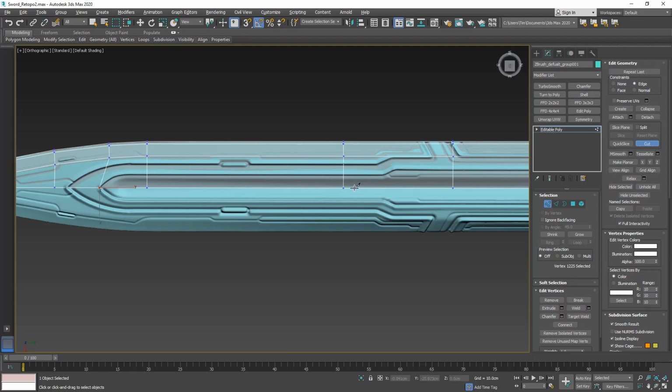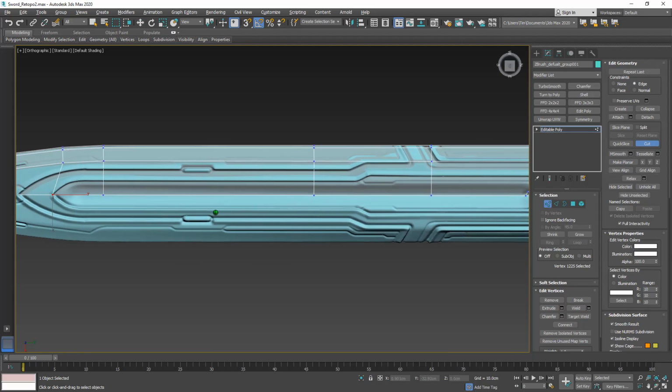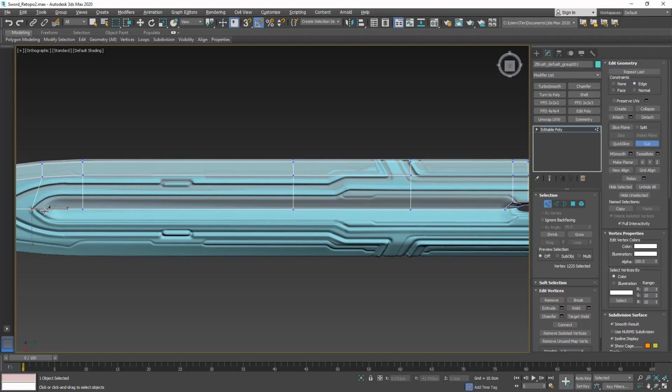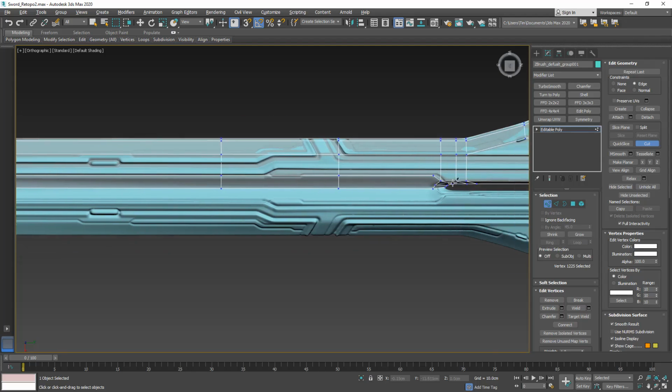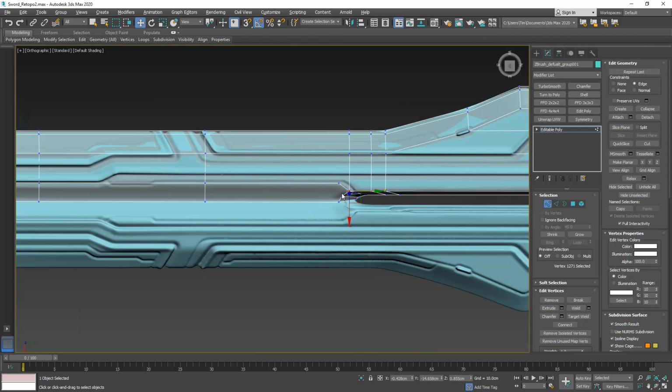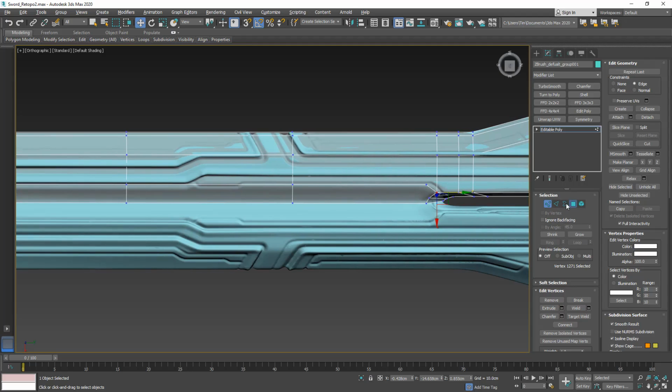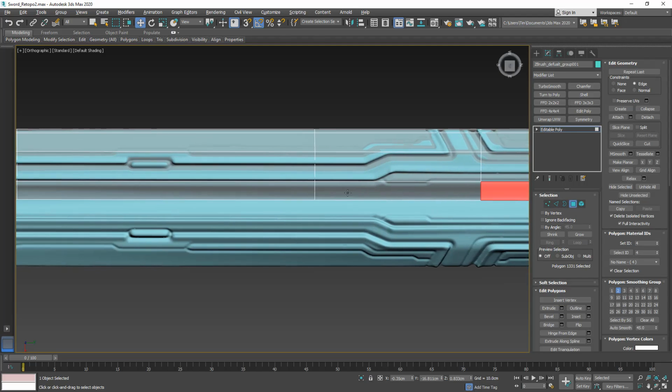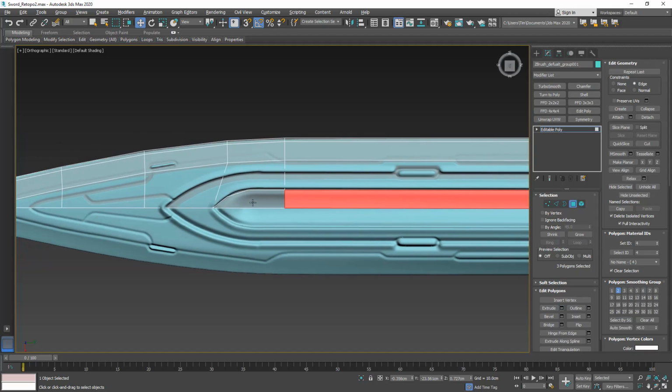And let's go back here to our cut tool on the vertex mode. And now I'm just gonna cut in already pretty much the path all the way here to where this goes. And then click down here and then connect it there at the bottom. Let's just double check that this is only one vertex. So I'm going to go out of the cut mode for that. And now we can select these polygons and then delete them.